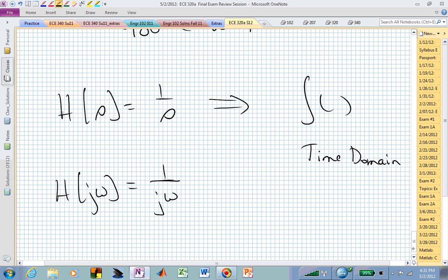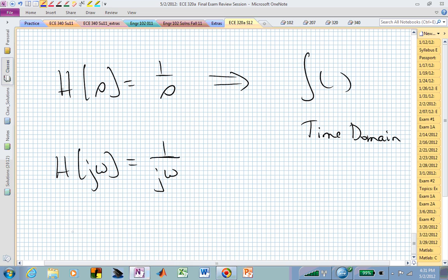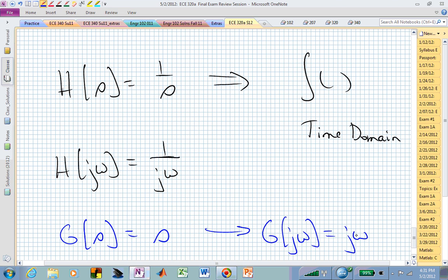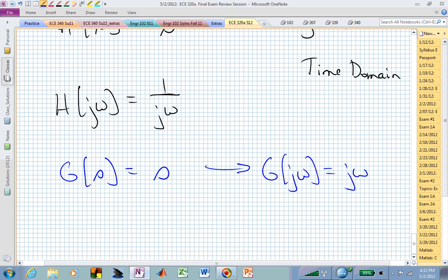Just the opposite happens if we had a transfer function that was just made up of a 0. I'm sorry, a 0 at the origin. This now looks like j omega. Now for tiny values of omega, it's tiny in magnitude. So we're starting really low in the dB scale, and as we increase the frequency, this gets bigger and bigger. And it never changes in terms of slope. It's always on. So we don't have this s plus a constant piece. When you do, that's when you have this break occurring. Does that help? Yes.